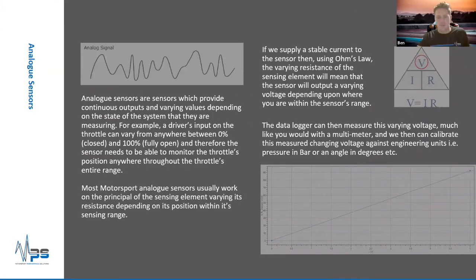So I've already mentioned some of the parameters. So we're talking about throttle application, steering application, all these sorts of things. So we need some way of monitoring them, measuring them. So one of the first ways, the prime way, is to physically attach a sensor to whatever we're looking at, and then wire that into your data logger. Then your data logger can process that sensor and save it in its memory.